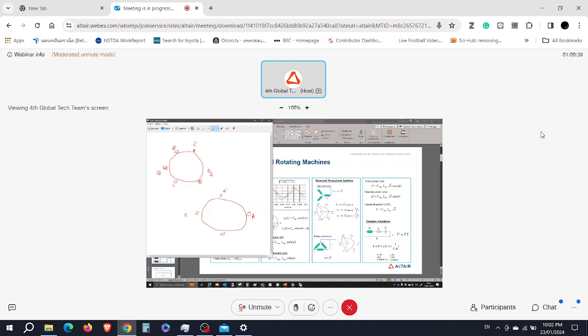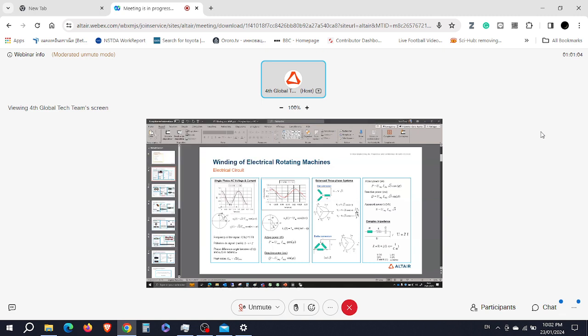In the case of distributed winding, you will see C prime, B, A prime, C, to add A, and make the row like this. So this is when we talk about 120 degrees as an electrical angle and not a mechanical angle.